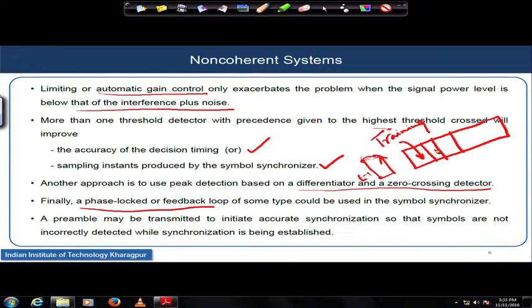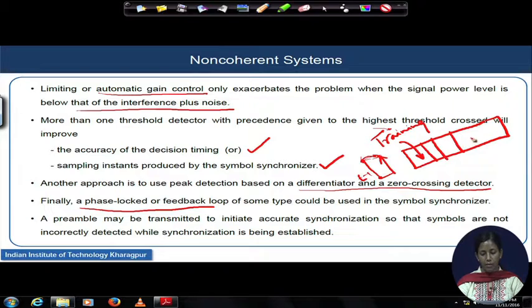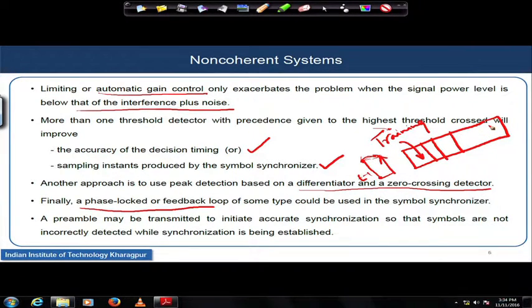Another way that we usually prefer is the blind estimation synchronization technique, where we do not transmit anything like this from the transmitter. Instead, we try to extract the statistical properties of the received data symbols and devise our synchronization process from the received data symbols itself, estimating the timing information from the received data or received payloads.